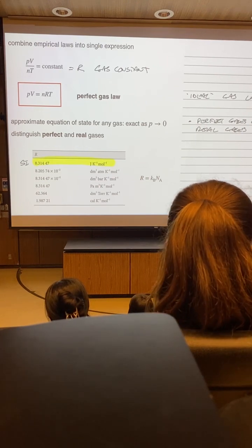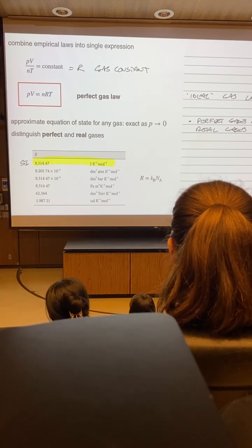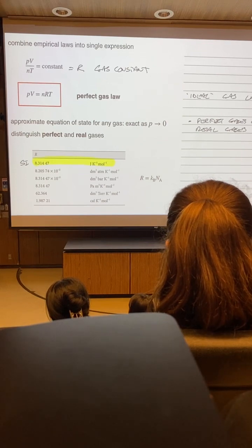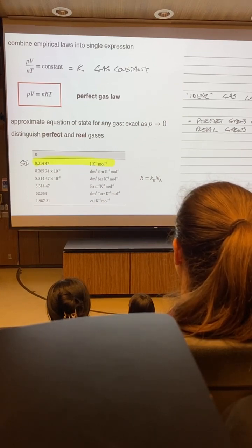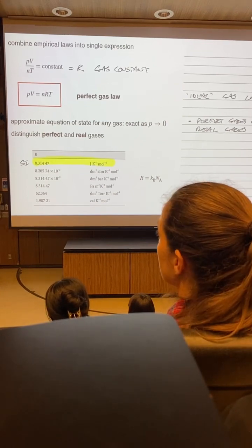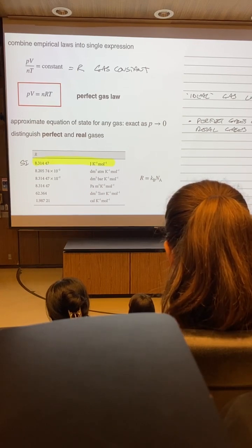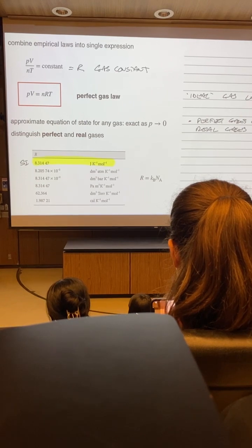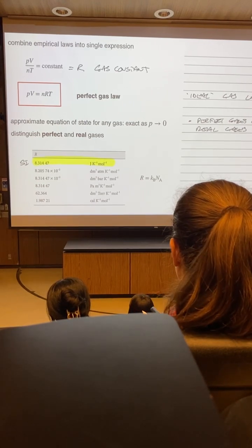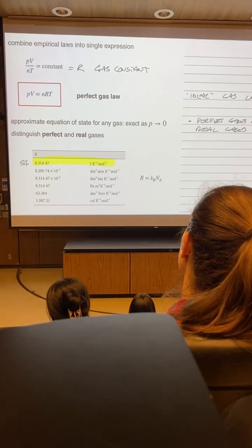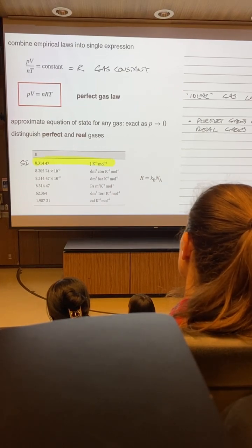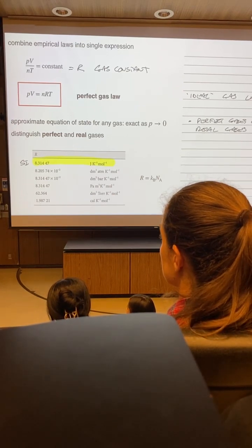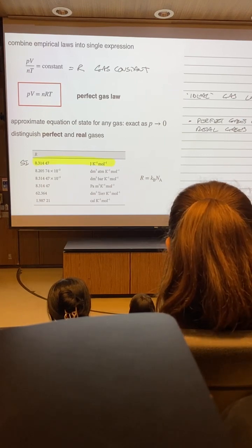Again, because pressures are often measured in units of atmospheres or bars or torr, or volumes are measured in liters instead of cubic meters, there's a whole range of different versions you'll see of the perfect gas law. Sometimes you might use energies in kcals instead of kilojoules. There's a version of that at the bottom of the table. So you have to make sure that whatever units your other properties are in, you use the appropriate version of the gas constant to match up.